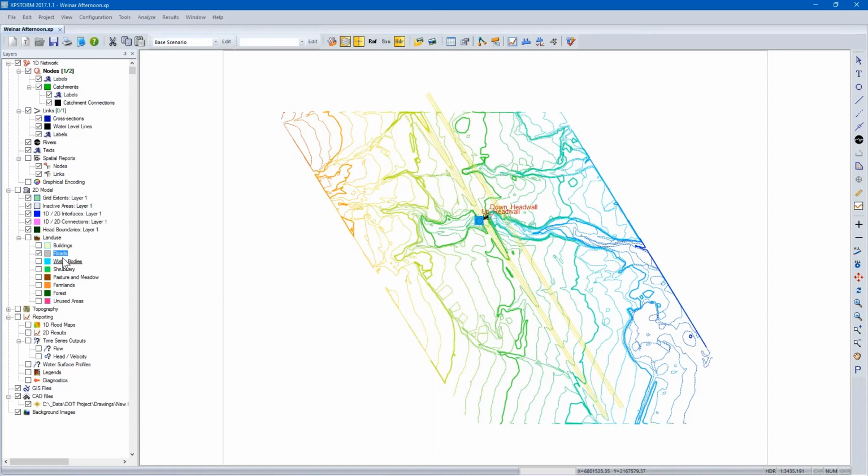So if I can come back to my roads, yes, if we have polygons that represent these land uses, we can import them. But I want to just select that, and I will just, again, use our polygon command and very quickly put in my rectangle that represents my roads. Take a little bit more care when you're modeling yours than I just demonstrated by snapping to 3 points. But hopefully to give you that idea of how easy it is to build an existing conditions flood model. So once we have all of that, we're pretty well ready to go. Before I do that, let me switch back.